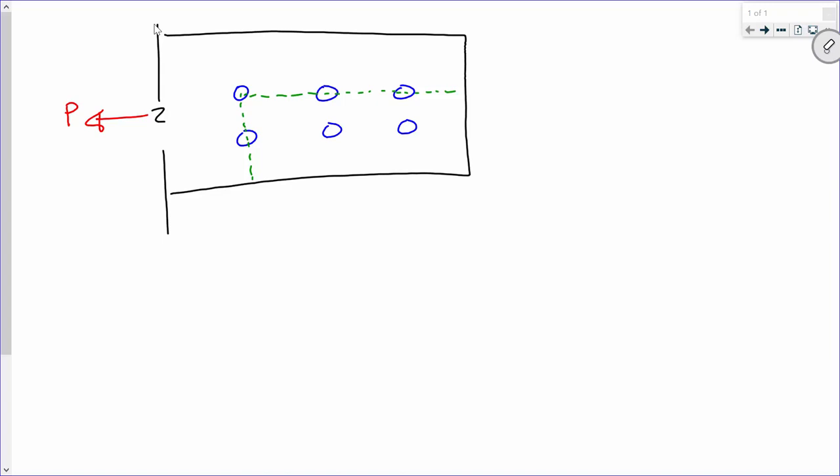The second point that makes this a valid failure path is that it, quote unquote, surrounds all the bolts. Let's keep in mind I've actually got bolts right here. I propose that if I took a samurai sword or lightsaber and cut the plate along this line, or imagine the plate was a sheet of paper and I took scissors and cut around that, I could separate that plate and the bolts would remain intact.